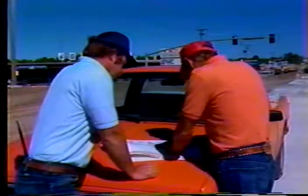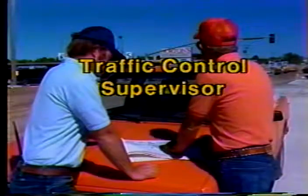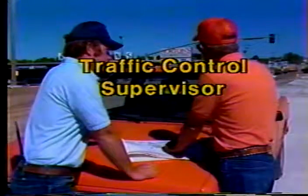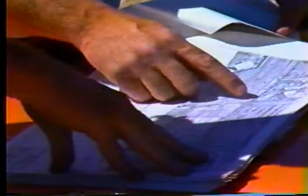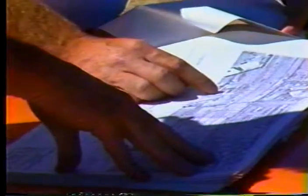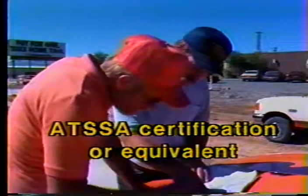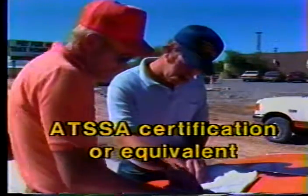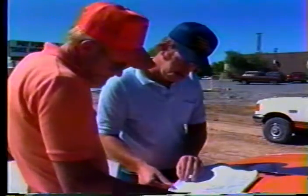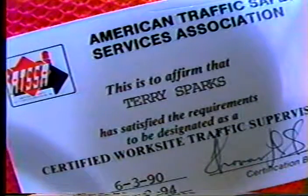In response to this principle, many agencies require the contractor to appoint a traffic control supervisor to oversee project traffic operations. This person must be well-trained and able to make traffic control decisions without consulting with his or her supervisor. Some agencies further require the traffic supervisor to be certified by the American Traffic Safety Services Association or to hold an equivalent certification. If that's the case, you should make sure the traffic supervisor's credentials are up to date.